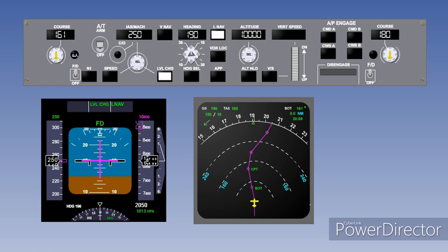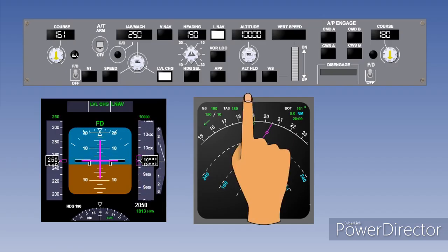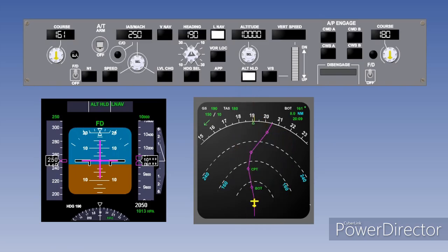As the aeroplane approaches the desired height, the flight director commands a level off attitude, and if the pilot did nothing else but level off, the aeroplane would then accelerate, so he also has to decrease the power available. He would also select altitude hold again to accurately maintain the desired altitude. The other means of controlling the vertical profile is by using a mode called VNAV, which has various pre-programmed climb and descent profile databases stored in the flight management system.